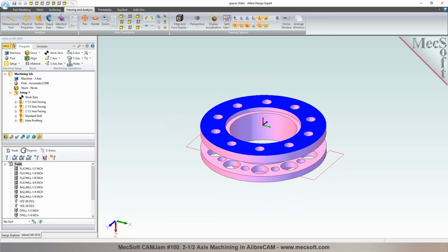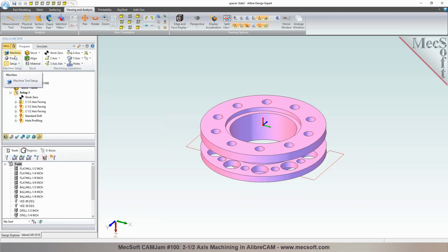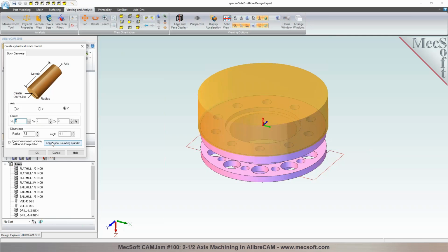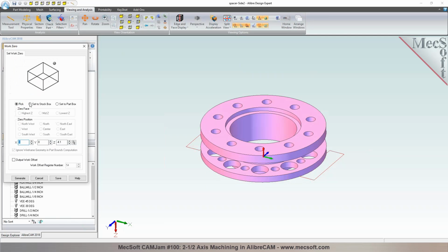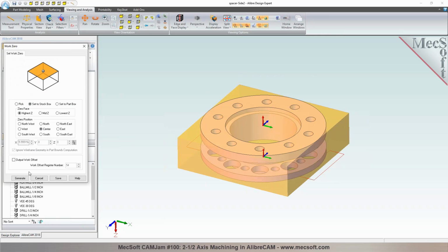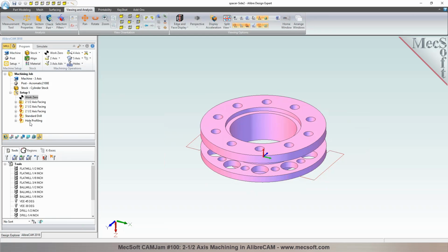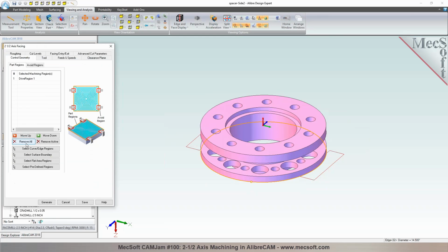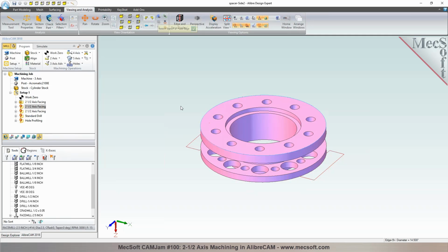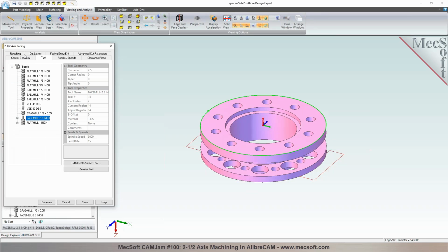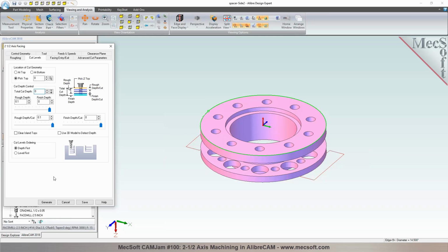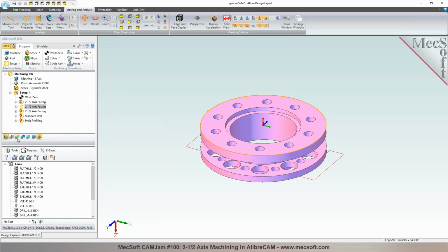now normal to this bottom face, and I could define the stock material in here, go back and define the stock, and I would basically define the work 0, and then program these toolpaths in here. So I can apply a facing operation. You can see that when I made a copy of the part, those operations were saved; they already existed in there. And then I would basically program these toolpaths.